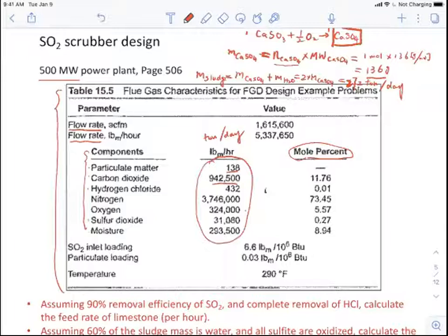Let's say that for the sulfur dioxide, if you come up with a value that's just 80 pounds per hour, you know that definitely there's something going wrong here. Because we're dealing with a similar scale of coal-fired power plant, the coal composition is similar. We should have something that's quite similar in terms of order of magnitude there.